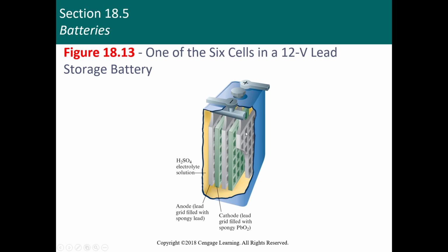this actually used to cause a lot of problems, and you used to be able to see people that worked with cars a lot, and a number of them would have burns on them. The reason for that is that people would try to fill up their water here to get their battery to work again. And if you're not careful and just pour the water in on a hot day, this can cause the sulfuric acid to splash back up at you, and it can get you in the face, arms, and burn you really badly. If you've ever seen what sulfuric acid does to people, it turns your flesh into this black goo. It's pretty nasty.